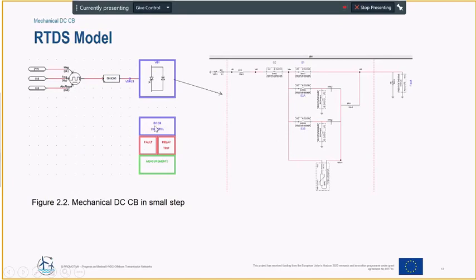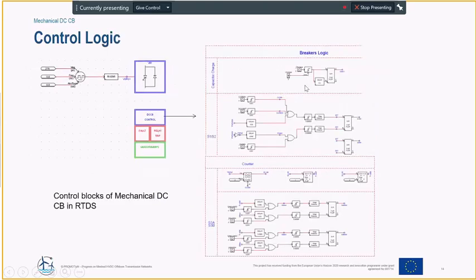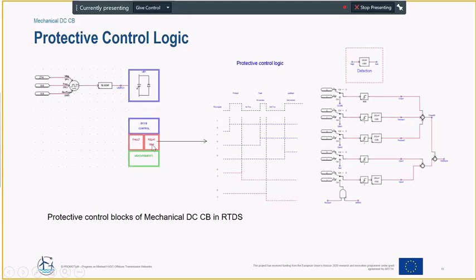There are also several other blocks that comprise the model. That's the DC circuit breaker control, that is here. So basically in this we have the breaker logic, and we also have the logic of the active current injection circuit. We also have a block related to the relay trip. So basically here we provide an external signal that may result from a physical relay, or it also may result from the model, so that this external signal should be given as a command to the breaker to activate the breaker and provide closing or opening operation.